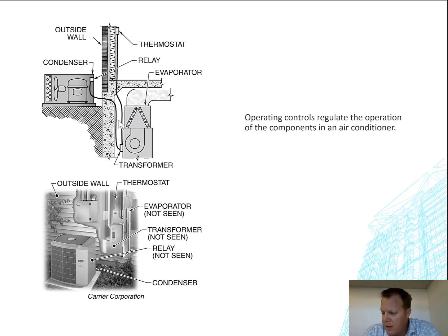We need a workspace in front of the furnace that's 30 inches deep and 30 inches wide. So we need some clear space, so we can't just jam this into the corner of a mechanical room without any clear space in front of it. Doesn't mean people like myself don't go put stuff in their mechanical room. But during construction, in order to pass your inspection at the end, we would need the space, right? We need physical space, clear space in front of the forced air unit.